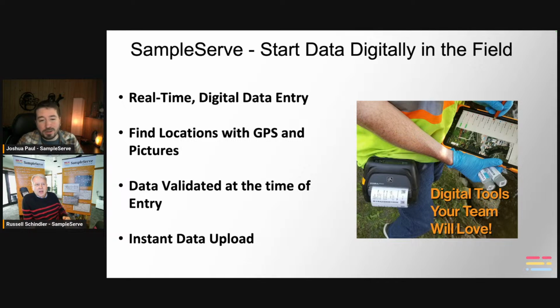And then with finding locations, with GPS, you can mark the GPS location of that sample location in the field app. You can upload the GPS coordinates in the work scope tool when you're making the setup. And then also you can take pictures of that sample location, in different angles, and you can show stuff in the background, so you can use those pictures to find that location super easily. Say, here's the tree, and the tree's right in front of it at this angle, the tree's next to it at this angle. It's right here. You start digging, you find it.